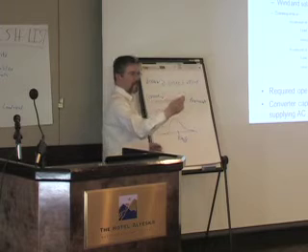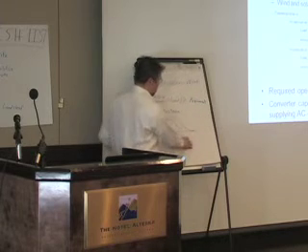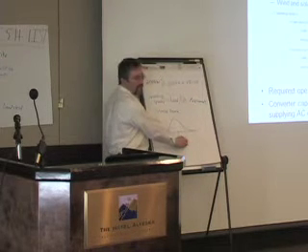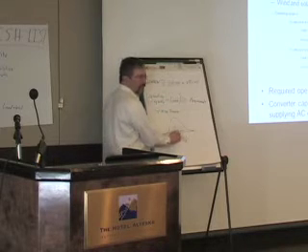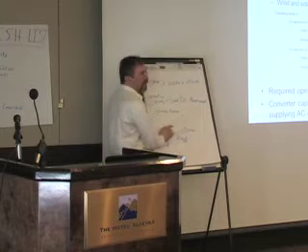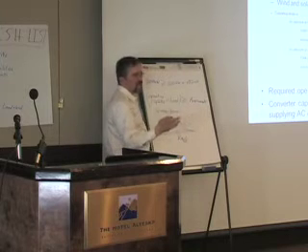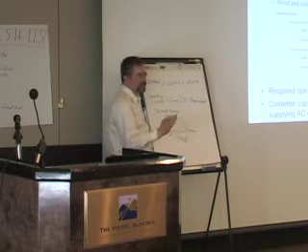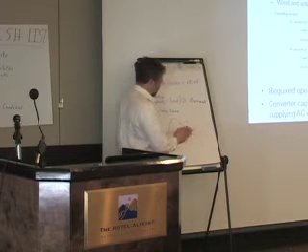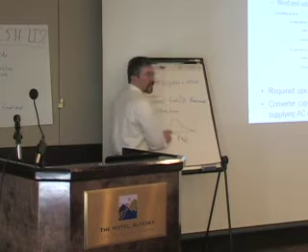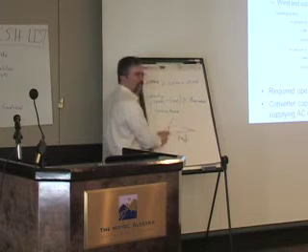Right now we're just asking for the mean wind speed within the time step, but if we also ask for the standard deviation, and we assume it's normally distributed, which within a time step is probably pretty reasonable, now we have this probability distribution.